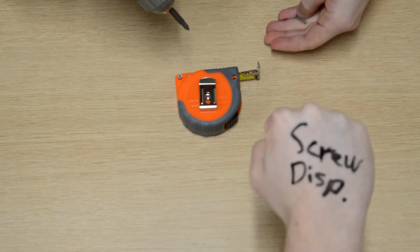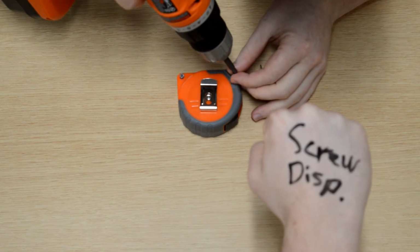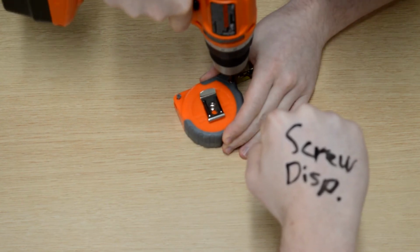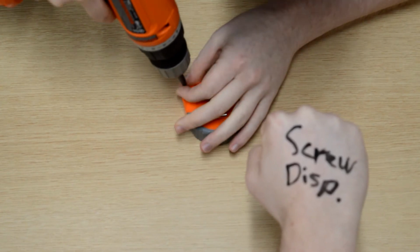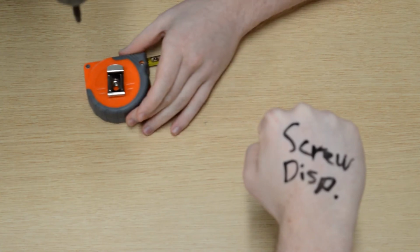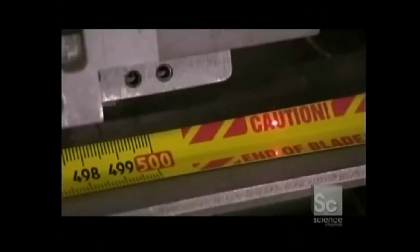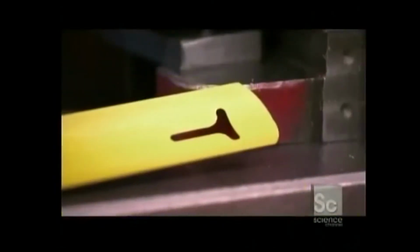We assume our demand is constant. As it is constant, a just-in-time system is able to produce with minimal buffers. Changing demand would benefit from changing buffer sizes or even an expanded inventory system. This is a risk all just-in-time systems face. Because of the constant flow and generally smaller batch sizes when compared to Western production systems, 100% inspection is feasible.